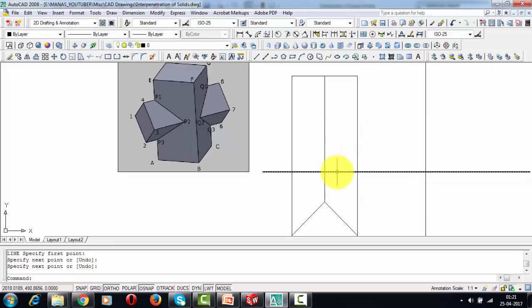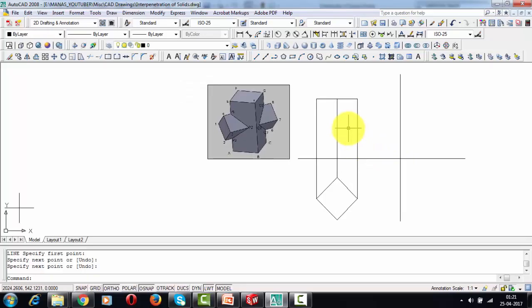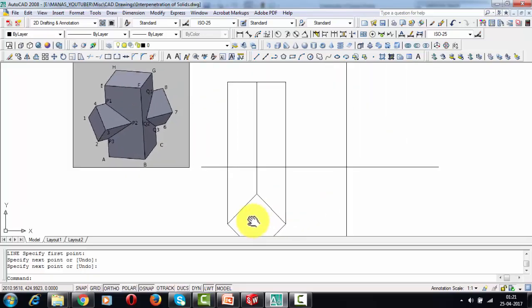All right. Let me darken this also. Okay, so right now we're going to be using a 4H pencil for this. If you're making this on a drawing sheet, make sure you're using a 4H pencil. And after the orthographic views of both horizontal as well as vertical prisms are done, it is then that we're going to be looking for the piercing points or the lines along which the penetration is really happening. All right, now we are a long distance away from all those things to happen. Let's now focus on this: front view is done, top view is done, and now let's create the side view.